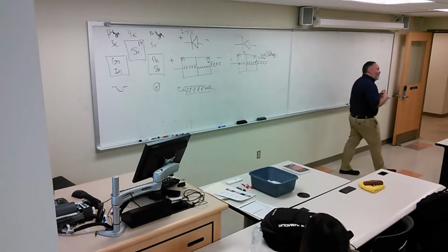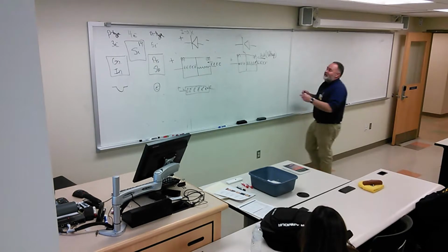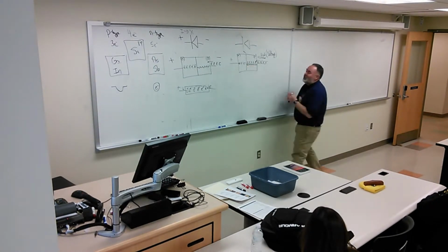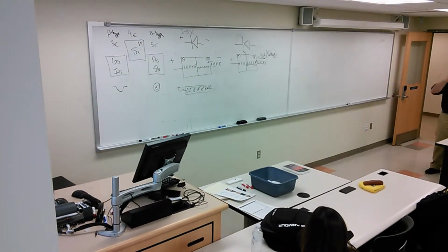And so when our Zener diode does not have a push, then those electrons don't normally stay inside there. And as soon as we stop pushing, those electrons come back. It's sort of like they're spring-loaded. It's not by design. They don't have real springs in there. It's all based on the electronics and the energy of this system. But what's happening is this bridge inside the material is extended while we push on it with the voltage. So until we push on it with the appropriate voltage, current does not flow because the bridge isn't extended yet.